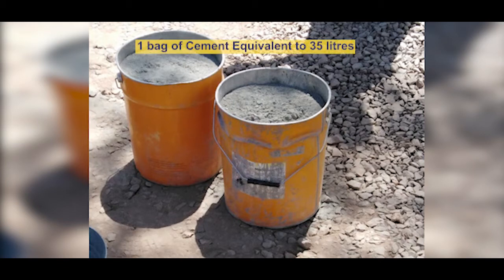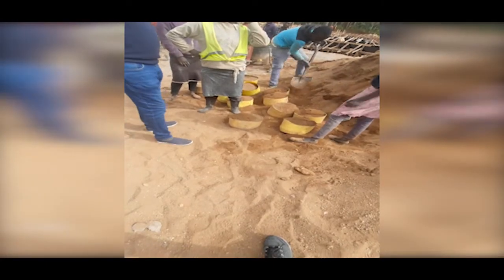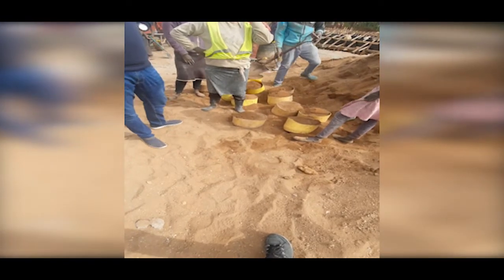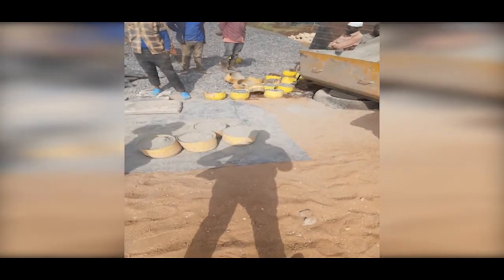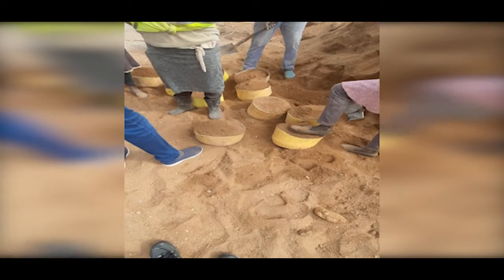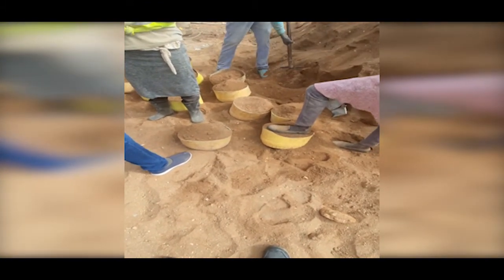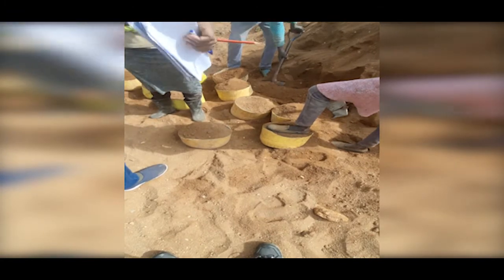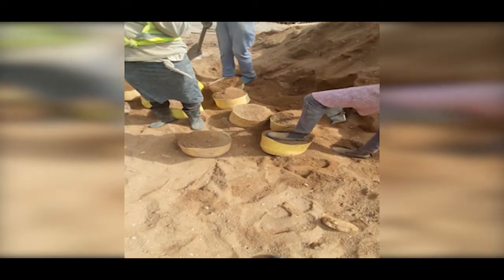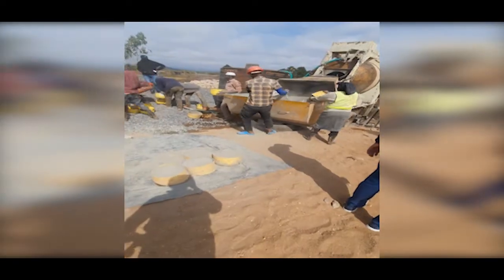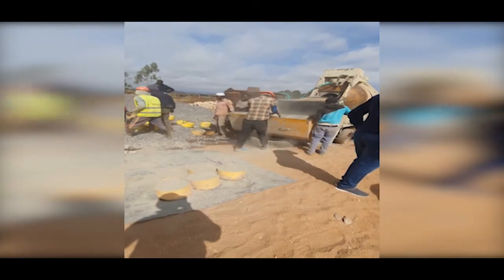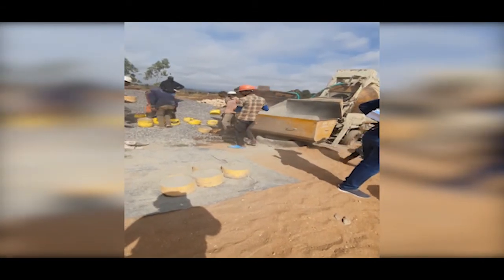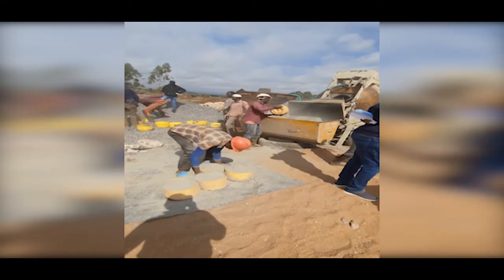So batching by volume, as I mentioned, is less precise, and if we can avoid it, then you're advised to do so, and rather go for batching by weight. Let's look at batching by weight. The components of the concrete, the cement, coarse aggregate, fine aggregate, and water are mixed on the basis of weight, as the name suggests. It is a more accurate method, and